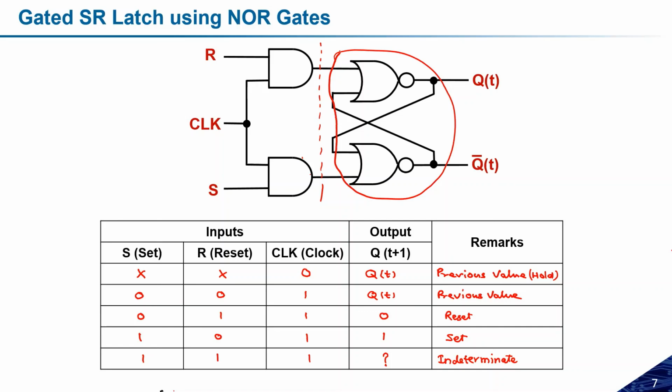But if there is an involvement of clock, then in combination we can call them the flip-flop, and this is the difference between latch and the flip-flop. Let me repeat it again. If there is no clock pulse, then we can call these kinds of designs the latch. These all are the latches. They are able to hold the logic.